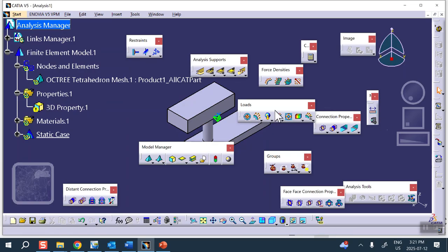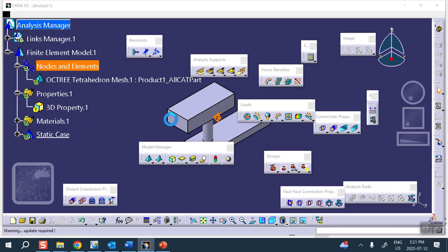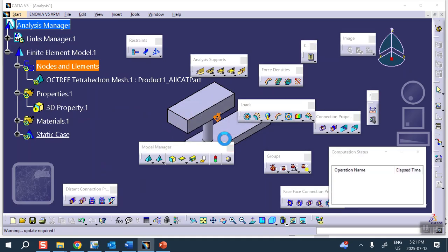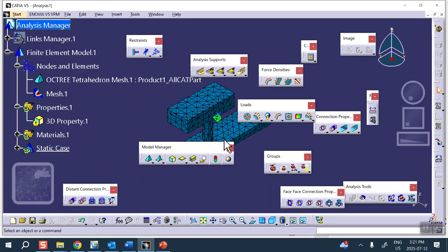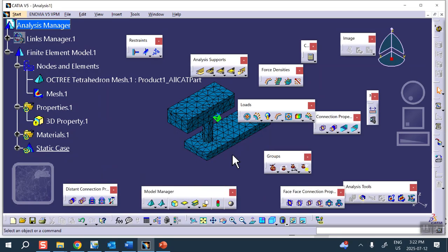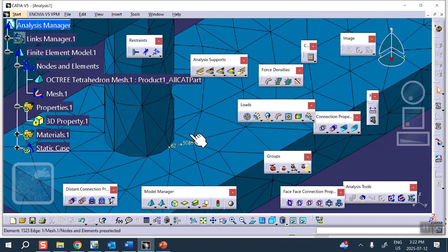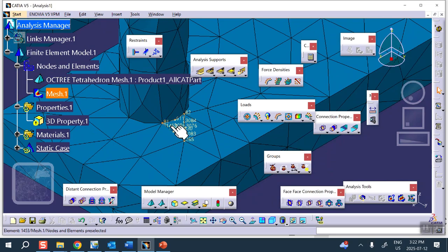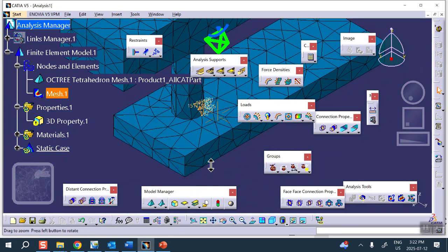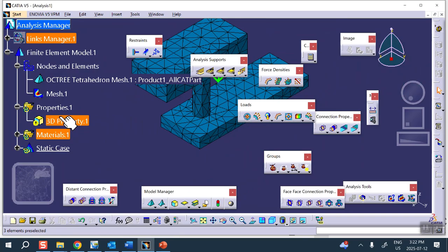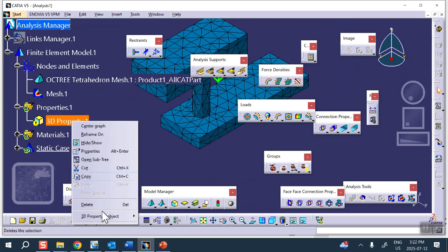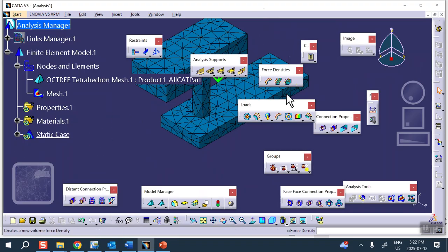So let's go and apply. By the way, we can see our mesh. Let's look at the mesh. There we are. And in fact, if you go and look closely, you see that the node numbers from the pieces are the same from this plate and from that. They're the same, 81, 82, etc. And the same thing up there. So it did actually mesh. It's just that the property is not correct. So can I delete this? Yeah. And then I'm going to do that myself.